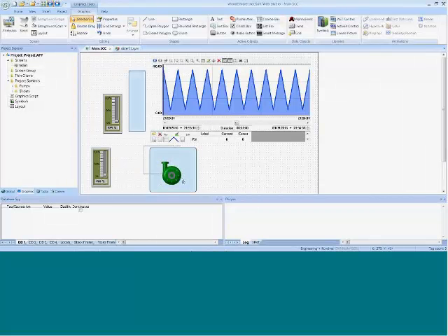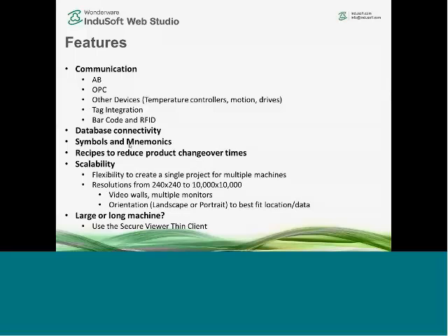And again, if you created a screen that was specifically like a pop-up screen, let's say, you could use that same symbol notation and pop up the pump configuration screen. And if you had 10 pumps, you wouldn't have to create 10 different screens. You can actually pass in those variables and only have to create one screen. And that's using a concept that we have called Mnemonics, using that same notation. We've got a really good webinar that was done just a few weeks ago up on our website. I highly suggest that you take a look at that and see some efficiencies there.